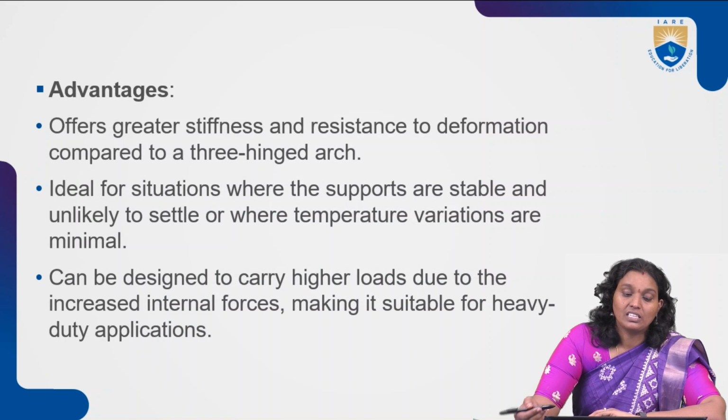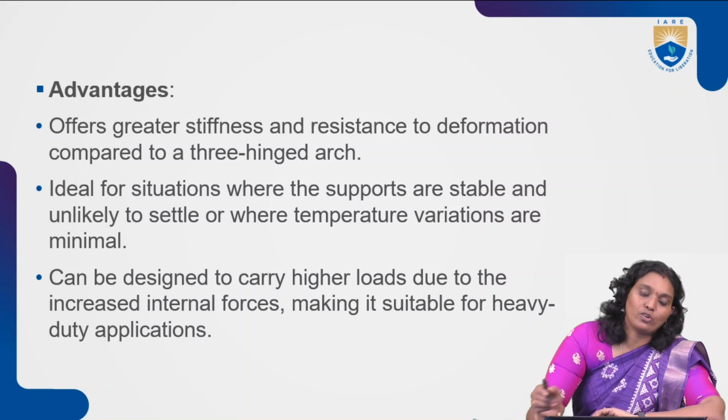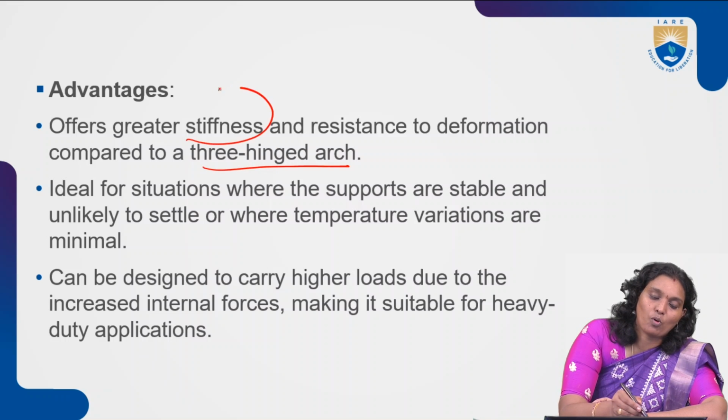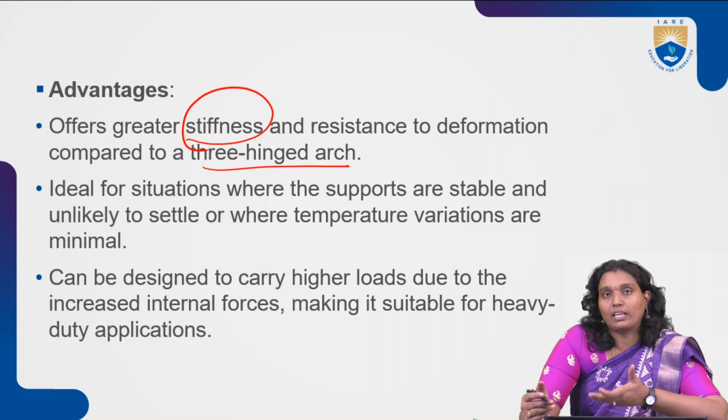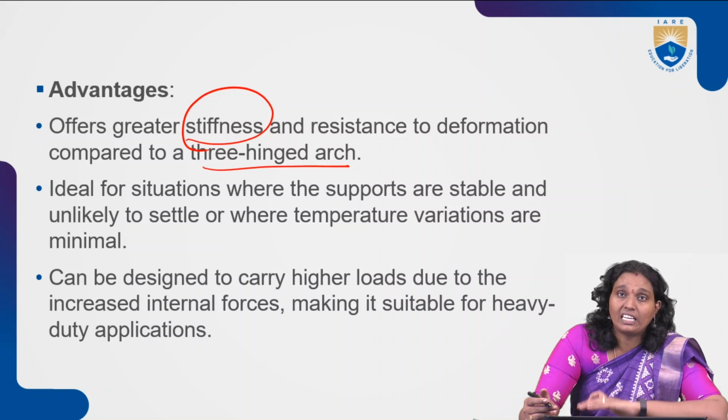So it offers the greatest stiffness and resistance to deformation compared to the three-hinged arches. From the stiffness point of view, it has more advantage because there is no additional crown hinge. Sorry, the crown is there, but there is no hinge at the crown, and that offers this greater stiffness and resistance to deformation when compared to the three-hinged arch.